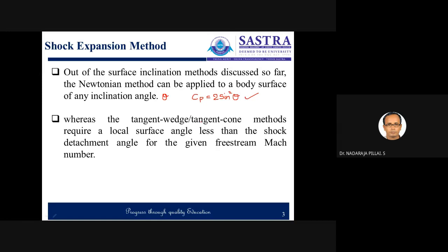But the tangent wedge method or tangent cone method requires a local surface angle, and that angle should definitely be less than the shock detachment angle, because the shock detachment angle is calculated at the nose for a given Mach number.